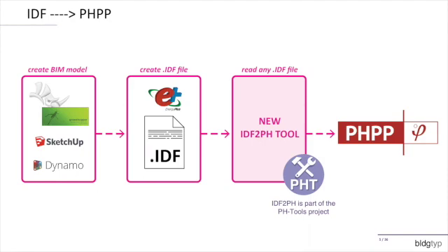This tool allows us to much more flexibly connect our own PHPP models to a more complete building information source model. So this IDF2PH toolkit is capable of creating a full dynamic energy model using the US Department of Energy's Energy Plus engine. And at the same time, we can create and control a complete PHPP model. So this toolkit allows users to super easily work through the Rhino, Grasshopper, or Dynamo environments using Rhino inside if you want to work in Revit. And this means that we can have a single source model drive our entire simulation and certification process, which is going to really reduce, or has for us anyway, really reduce the modeling time, the complexity, and most importantly, eliminated a lot of errors.